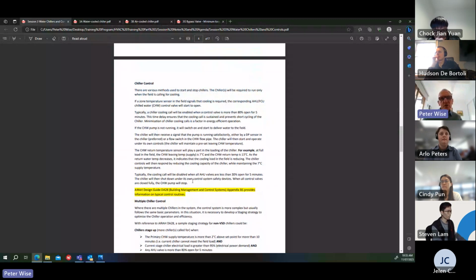So I say that when we get into more complex systems, which we're going to talk about a bit today, bypasses can get quite complex. I worked on a project a long time ago, a very big project. It was a resort, hotel, casino, convention centre. But that was in the days before we had variable speed drives. It was just a constant flow system. We had 3 bypasses. The 3 bypasses were all different sizes, and they came into play at different points of the flow.